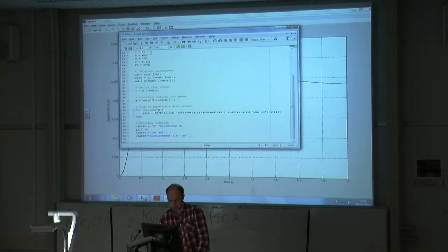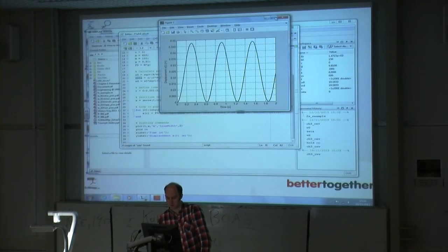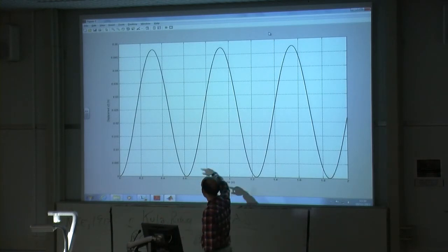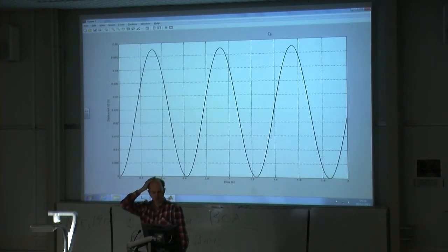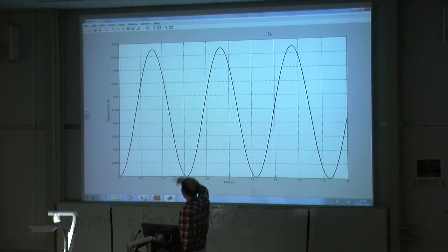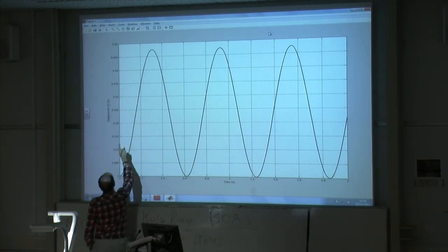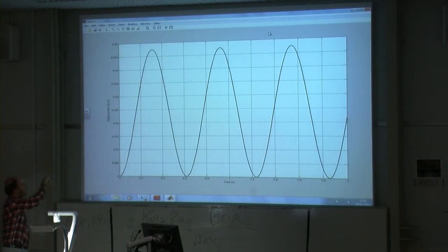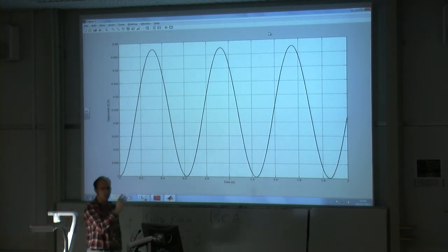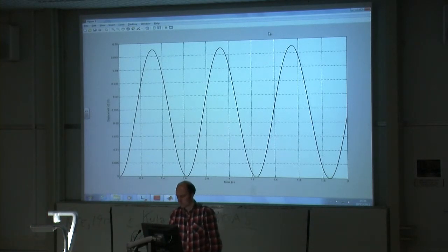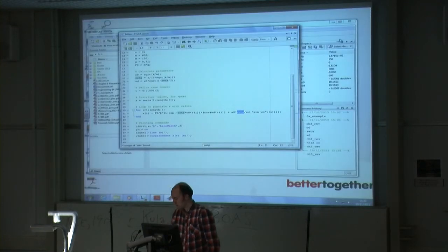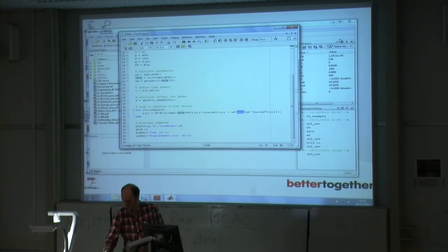Okay, and obviously you could even reduce the damping down to 0. And notice what that does. That means that this term here, zeta, becomes 0, so the sine term just disappears, and you end up with a solution for the case when you've got no damping, which you've seen before in some of the solutions to the problems that you've had. It oscillates up and down. The centre point is 0.0237, the constant value, but it oscillates 2 times that back to 0, 2 times that back to 0, and so on. And we'll do that forever because there's no damping. Okay, so that's the solution to that problem.